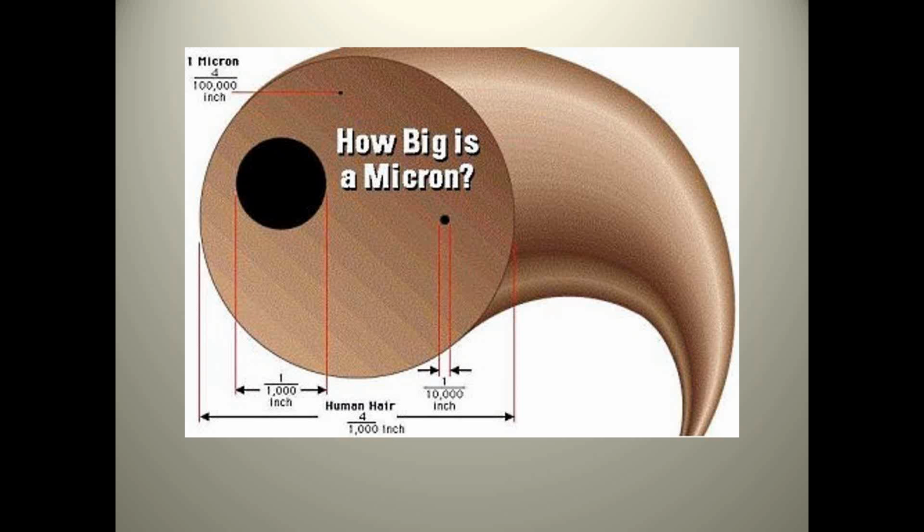But what they're trying to demonstrate here is a human hair, and they're trying to say they don't want any particles around that 30 or 40 microns in size in their oils. They'll try to get some of those small ones. They don't really worry about the ones that are 1 micron. But you can see that if we keep these particles out, Caterpillar has proven with their equipment since the mid-'80s that their equipment actually lasts longer. So again, this is another illustration of the same things we can do with our industrial equipment, the same things we can do with our mobile equipment.